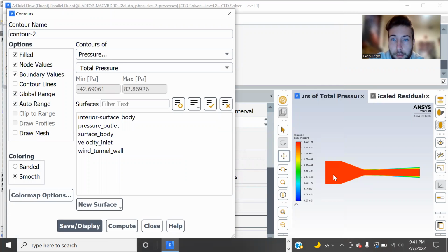Constant basically throughout. That's the way it should be. The only issue is you'll see these boundary layers that develop. And it's super interesting because we've got turbulent flow. So we're of course going to have a boundary layer. It widens as the flow develops. And that's where we see pressure loss because of viscous effects. So you can see that pressure's gone down. And that is very notable.